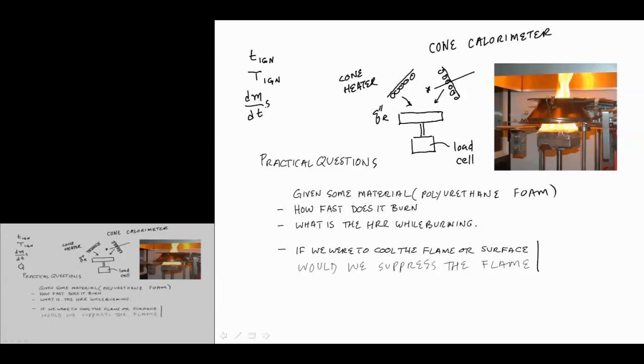The way the heat release rate is measured is once this sample starts to burn, the products of combustion are collected and a gas analyzer system analyzes these products.